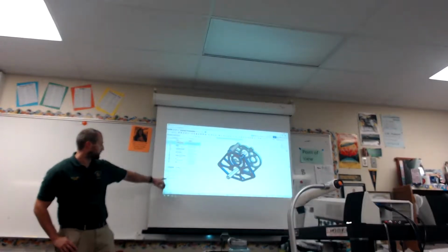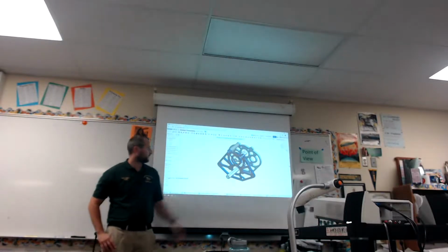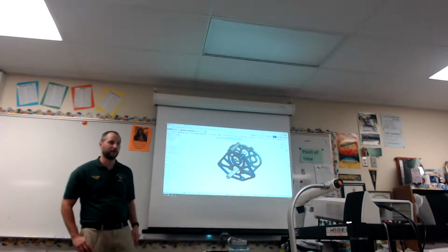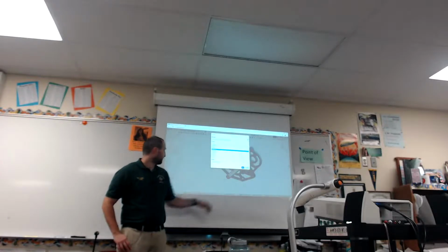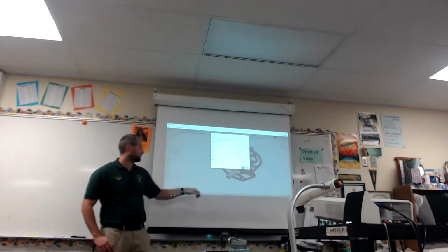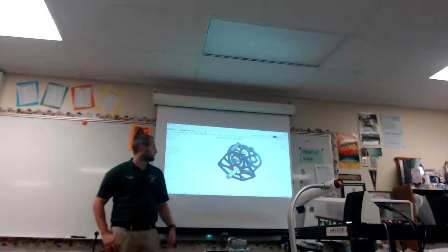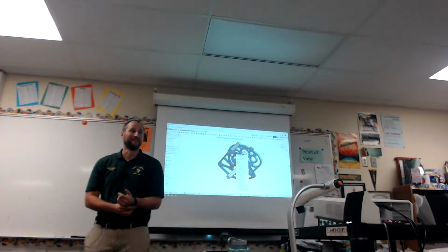So here in the bottom, you can see there's a parts list here. You can also just right-click on any of those parts and export. You just export right there. You can export to all the different formats, STL, et cetera. You can export the full part studio if you wanted to as well. Right-click on one of those gearbox plates. You can export it from there as well, so you don't have to go hunt it down in there.